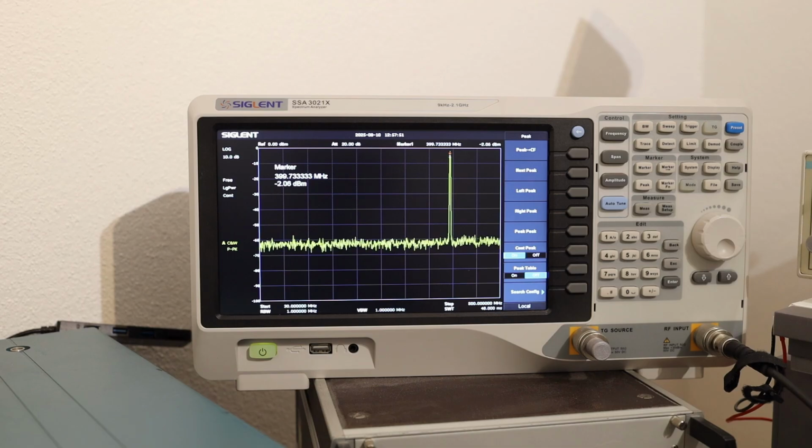It automatically went to 400 MHz, and signal amplitude dropped a little bit as well. So now we will try to show you how well the sweep works. 35 or maybe like 100, or maybe say 300 to 500, and we got a step of 10 MHz, 100 millisecond loop, start sweep. So you see it's sweeping, and now I'll change the spectrum analyzer span so that we can see the signal from 300 to 500 megahertz.